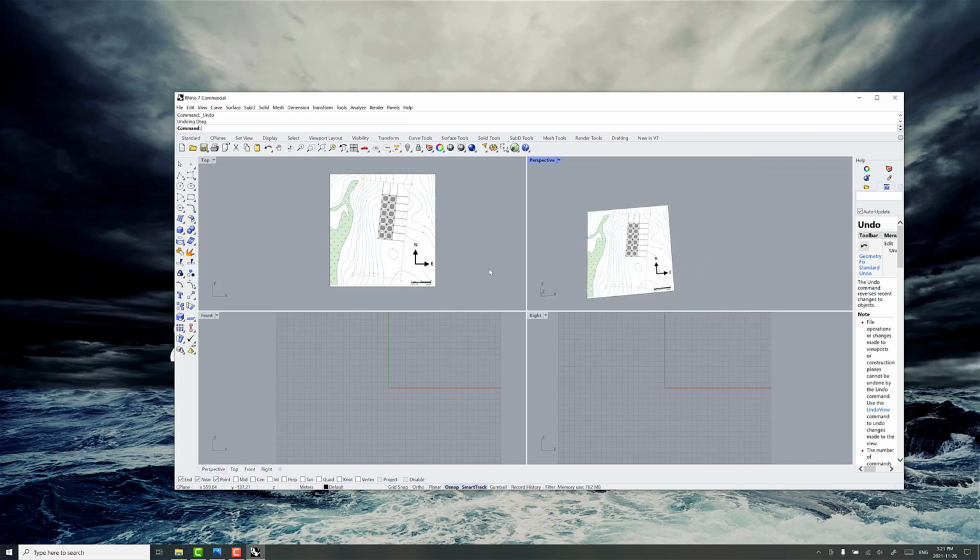The easiest thing to do is complete the rotations now with the image, before we start drawing out the bathymetry mesh. First, in the top view, we're going to make a rotation so that the northern direction on the image lines up with positive X. So go to the rotate command, select the image in this top view, press enter when done.